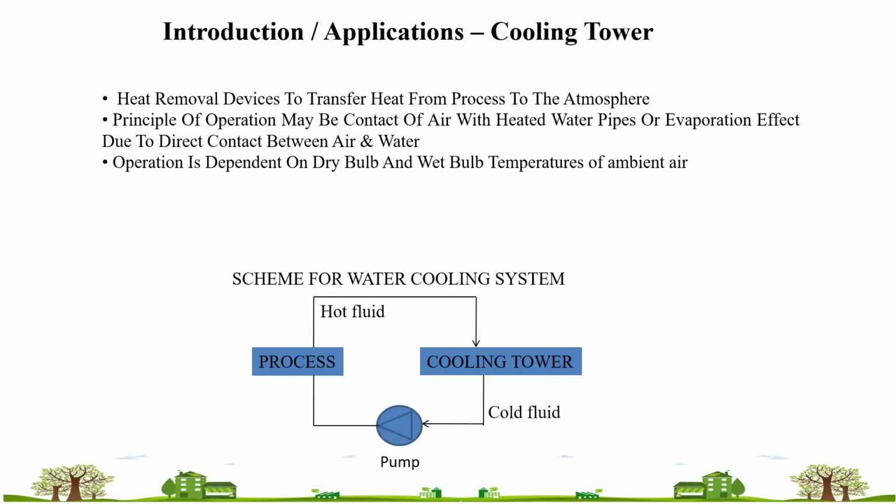If you are getting inlet process water at around 33, 34 degrees Celsius, and you are not cooling it down to 28 degrees Celsius, so the basin temperature is not 28 degrees Celsius, then the performance of the cooling tower is mismatched, or not that great, we can say. So these are the deciding mechanisms. Likewise, operation is totally dependent on your ambient air temperatures.